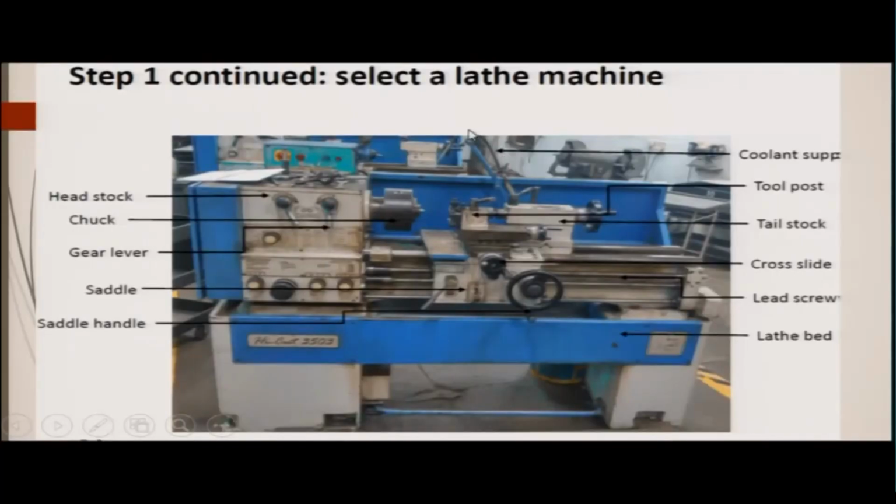Here we have the coolant supply. So, depending on the type of the operation that is being performed, you need to have the coolant supplied, and coolant will be supplied to the machining zone between the tool and the workpiece, because a lot of temperature is produced, a lot of friction between the chip and the rake face of the tool or the workpiece, already machined workpiece and the flank face and so on. So, those surfaces of the tool particularly have to be cooled down. Why do I say for the tool particularly? Because the tool surface has to be protected, otherwise the tool geometry will be lost, all right.